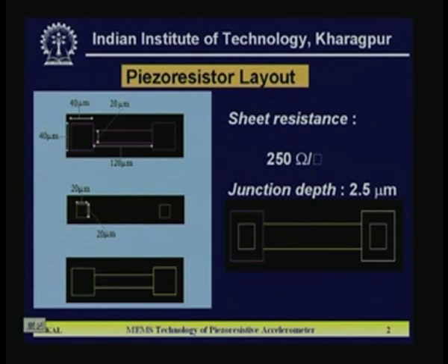But one thing I would like to mention is that in any diffusion technique the resistance variation after fabrication is nearly 10 to 20%. Most ICs are designed in such a fashion that even a 20% variation of the resistance values will be accepted by the designer. That means the design should be robust, so that with that resistance change the performance of your circuit will not be hampered much. Similarly, here also we assume even 10-15% variation, and the complete circuit should work.